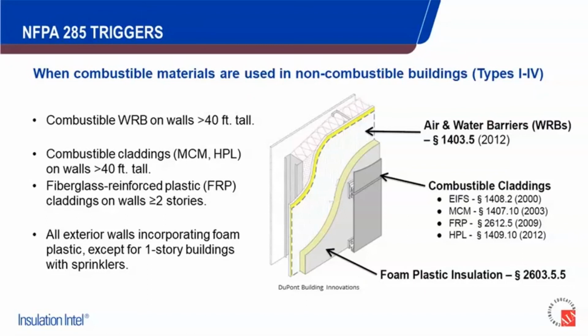The exceptions were pretty important, I would say, maybe just a few years ago, and I'll explain why that is. And I would say they're less important now. And we'll get to that in a second here, but some of the exceptions related to water resistant barriers: if it's of course a structure that's 40 feet or lower, you're going to have an exception. That's not going to be a requirement.